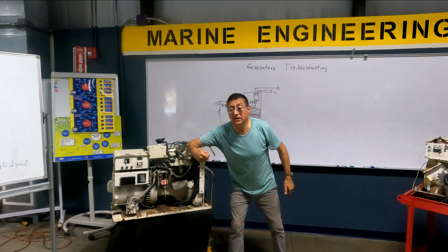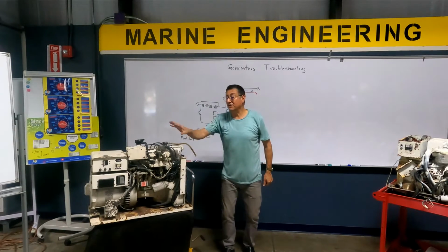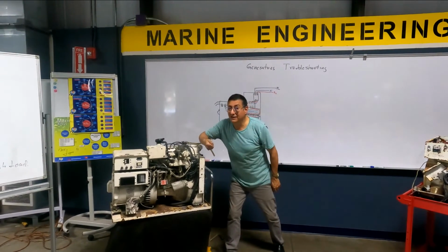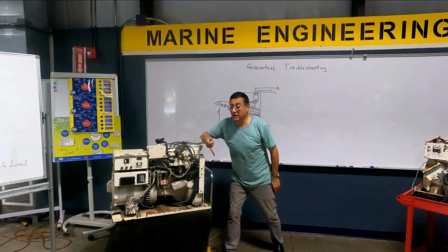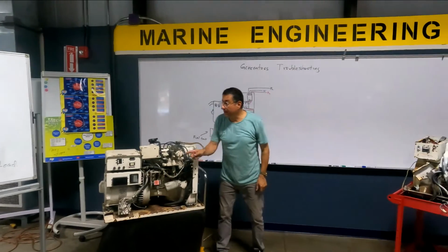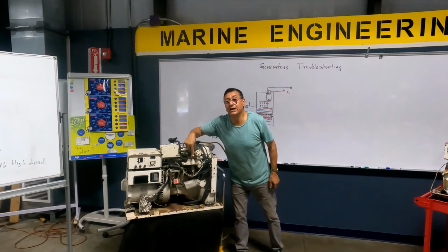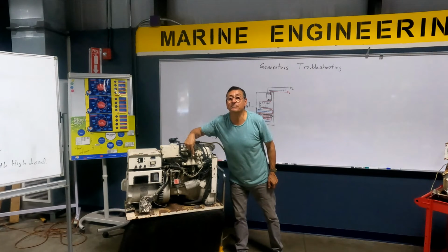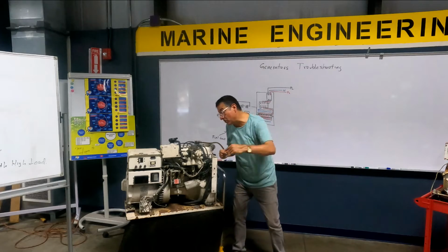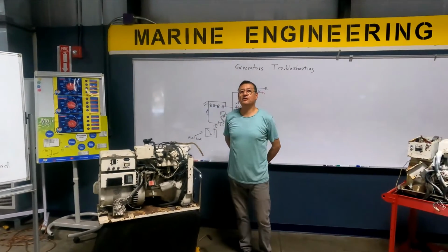The engine is cranking. Start, but immediately when I remove the key, the engine stops. Where is the problem in this gasoline engine? The engine starts. When I remove my finger, immediately the engine stops. You need to verify if, when you remove your finger, the current in this solenoid is interrupted. How can you do that? You disconnect here and you bring direct current directly over there. And now it starts and continues running.